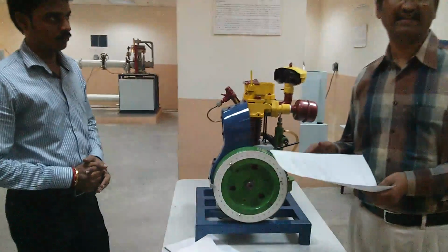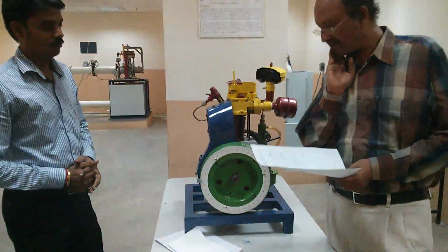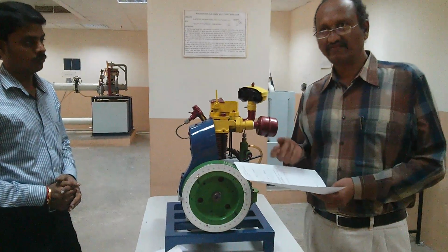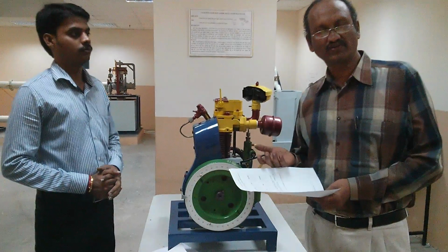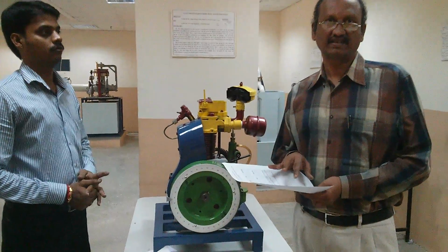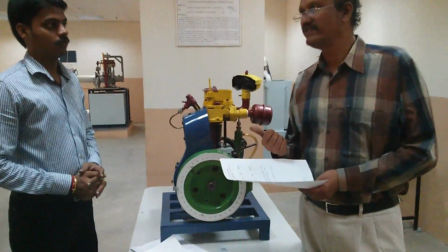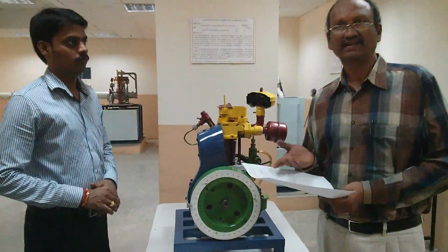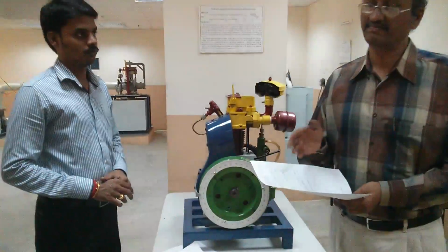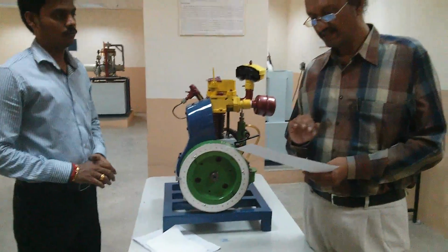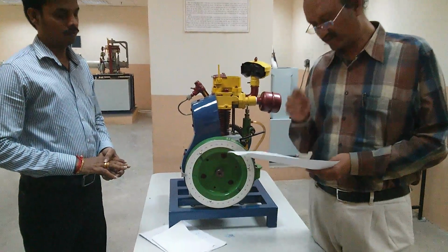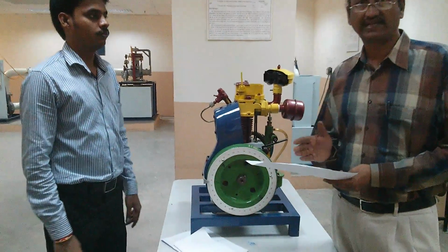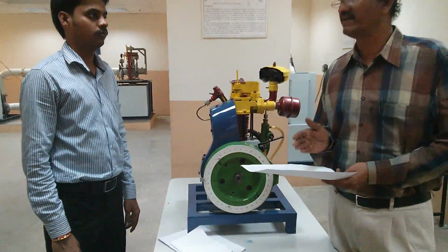But this is the theoretical valve opening. Practically, in order to get maximum performance of the engine, the valves are opened and closed at more appropriate timings so that you are getting maximum efficiency from the engine. That means the valves are not opened and closed at the dead centers. They are opened or closed a few degrees before or after the dead centers. So that's what we want to find out, and we want to diagrammatically represent at what instant the valve is opening and at what instant the valve is closing.